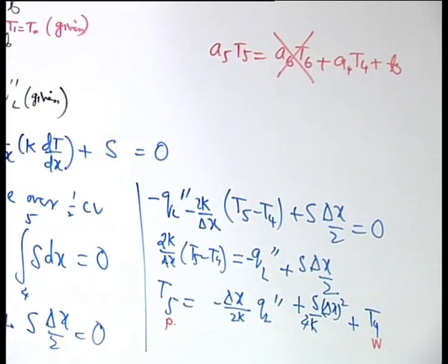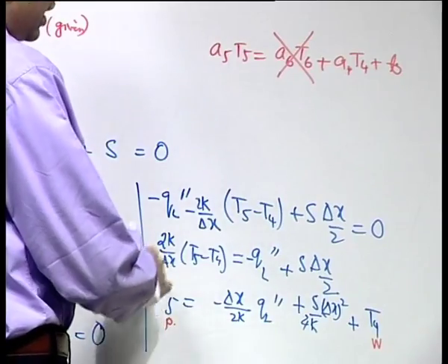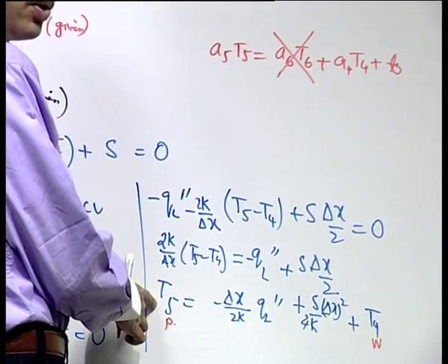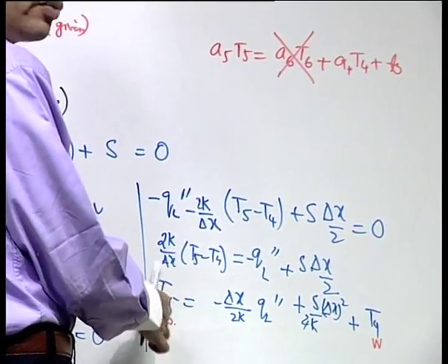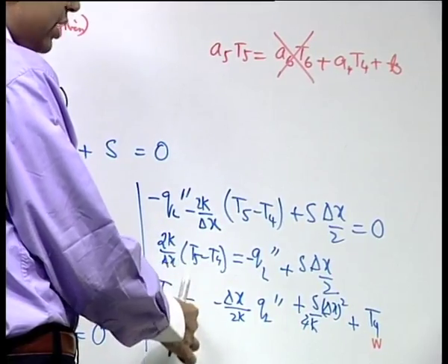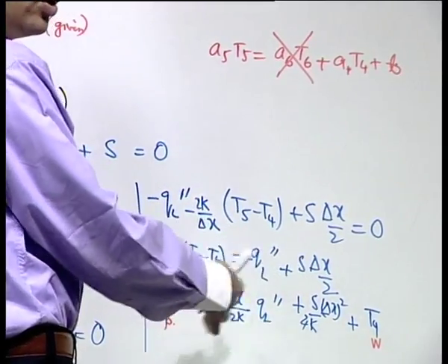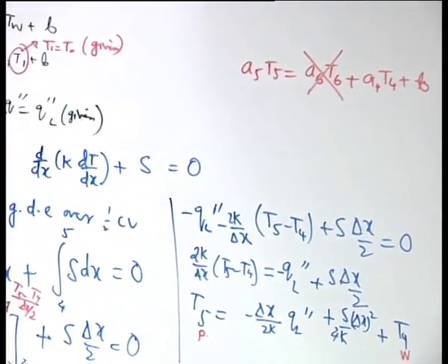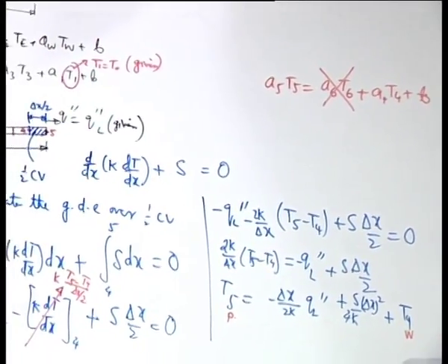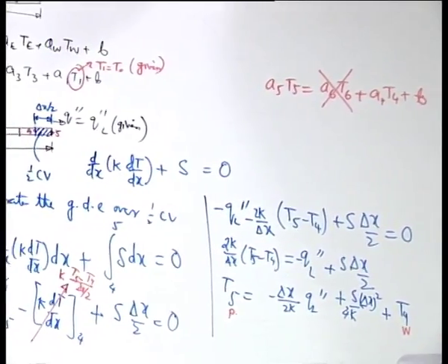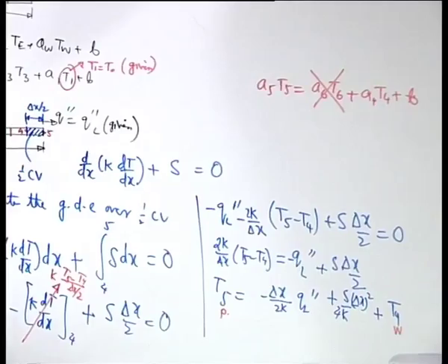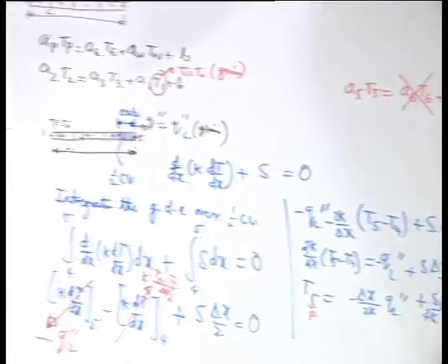And again see, we are organizing the equation in such a way that it is a governing equation for temperature at the grid point 5. So, that comes in the left hand side, that means boundary as a function of the interior, that is how we are writing it. Now, it may be interesting to compare this implementation of boundary condition with the common finite difference based implementation of boundary condition for the same problem.